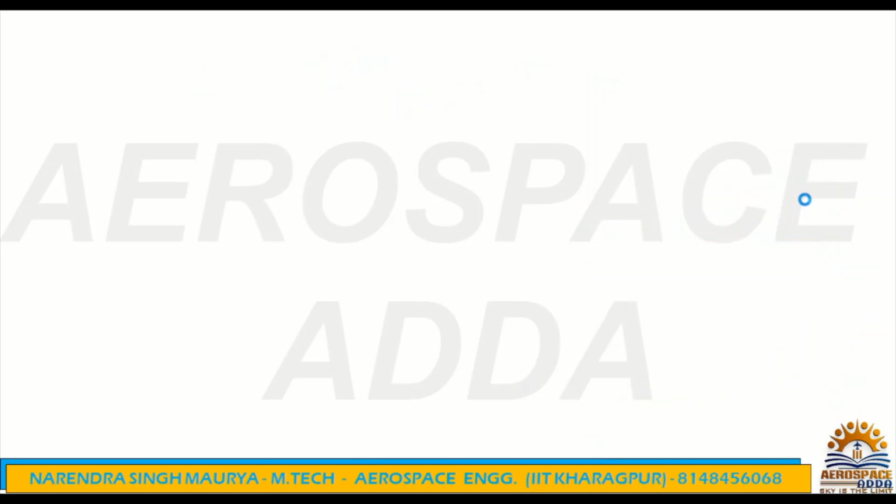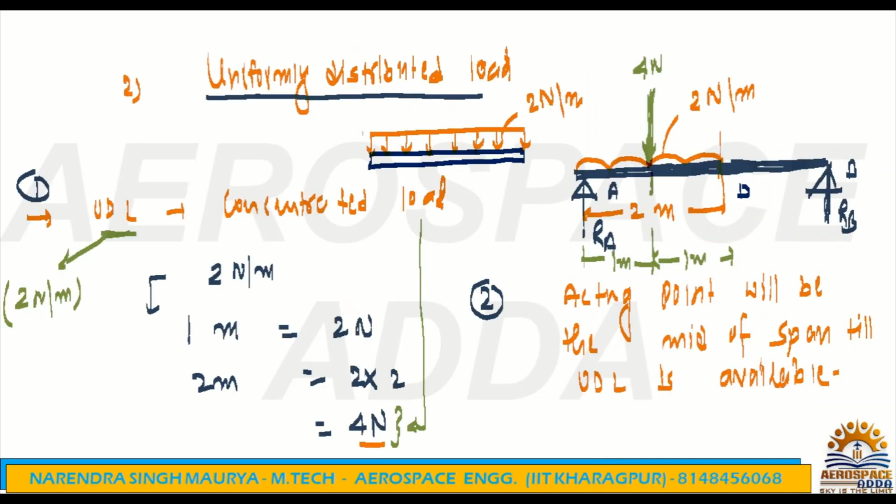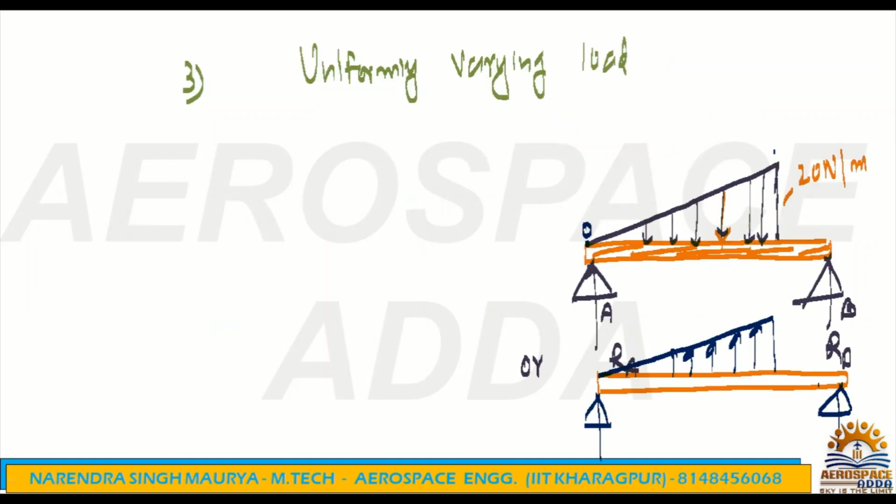But here, if you see, it started at 2 Newton per meter, so here also it is 2 Newton per meter. That's the reason this is called uniformly distributed load, but this is called uniformly varying load. Here it is varying continuously. Hope you understood. Now how to calculate this?